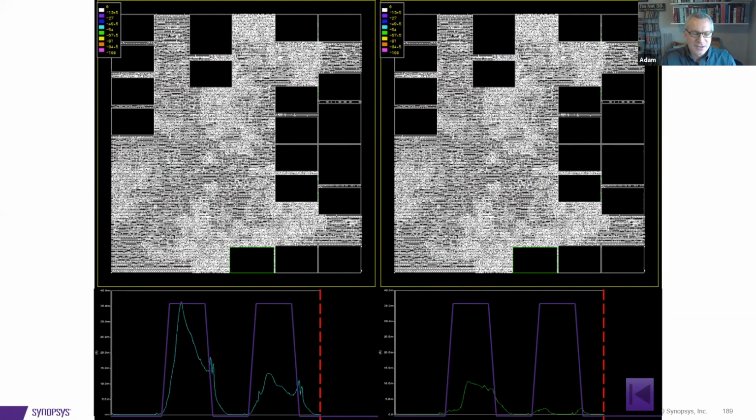That's why I said that for wrap designs, the tools can automatically drop in clock gating so that when you turn off a design from a DFT standpoint, it can actually turn off all the clocks inside the design to keep it quiet while everything else is clocking and pulsing.